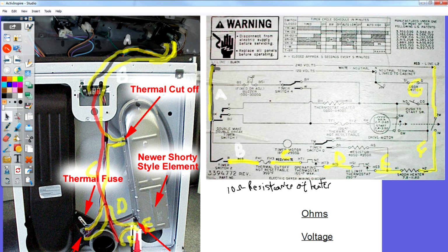Now, I can also do a voltage test at that same point. I'm going to put my meter leads back on the diagram for a second now, because I want you to see something. First of all, how much voltage should I have at that point? At the heater? Yes. You should have what? 240, no? Yeah, the diagram up here says 240, so line 1 is here. And this little line here, by the way, guys, is not a wire. It's not an electrical circuit. They're just saying from this dot to this dot way over here, I have 240 volts.